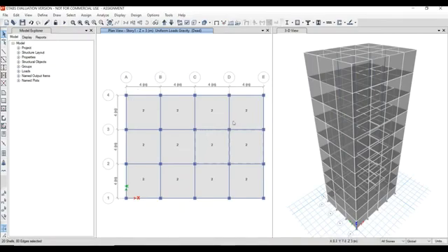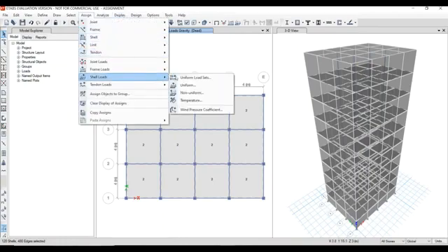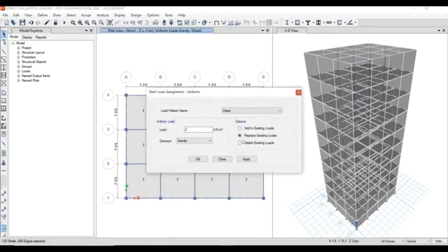Now the same thing you need to do to assign live load. So select every shell again, or else you can use select previous selection, so that all the shells which we previously selected get selected. I will show that some other time. So 120 shells are selected. After selecting the shells again, assign shell loads, uniform loads. Change the load pattern to live load.